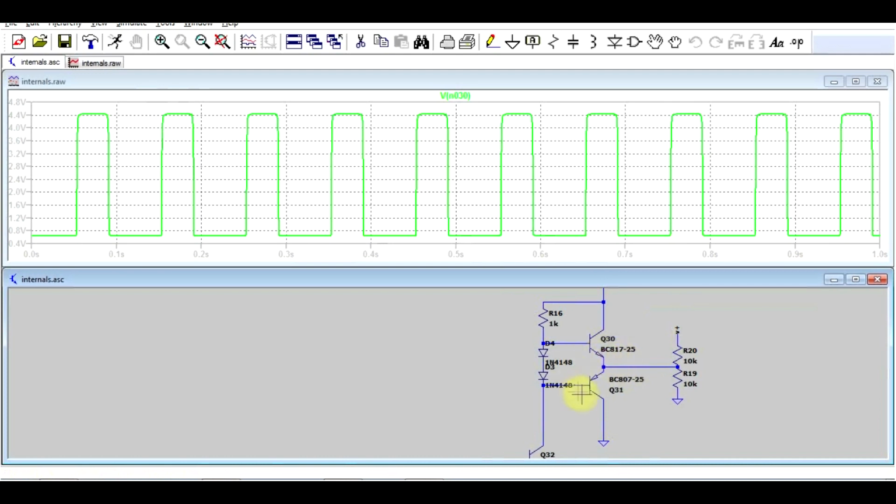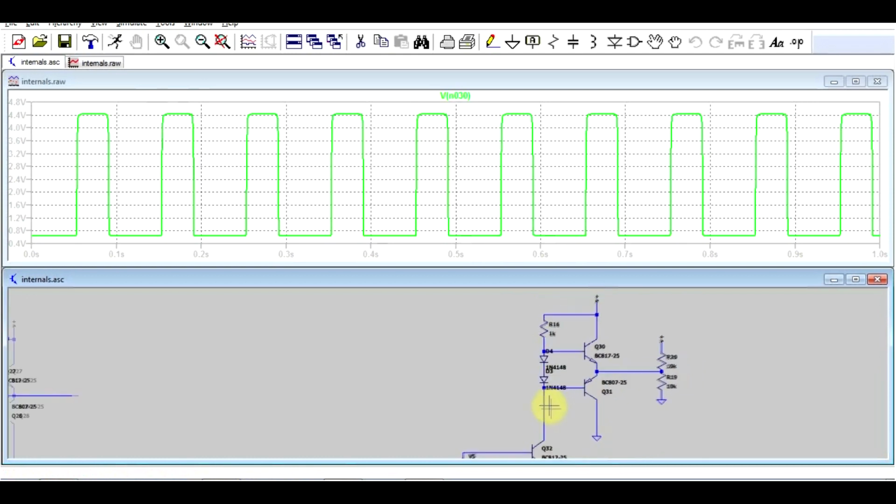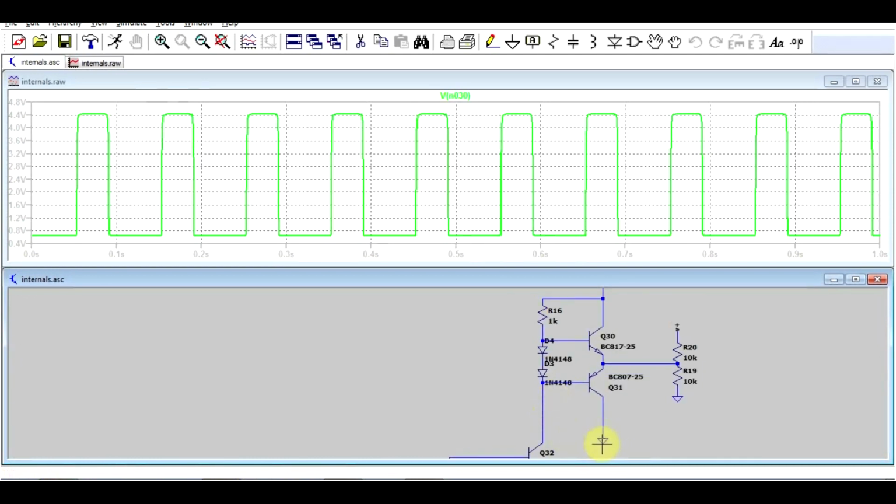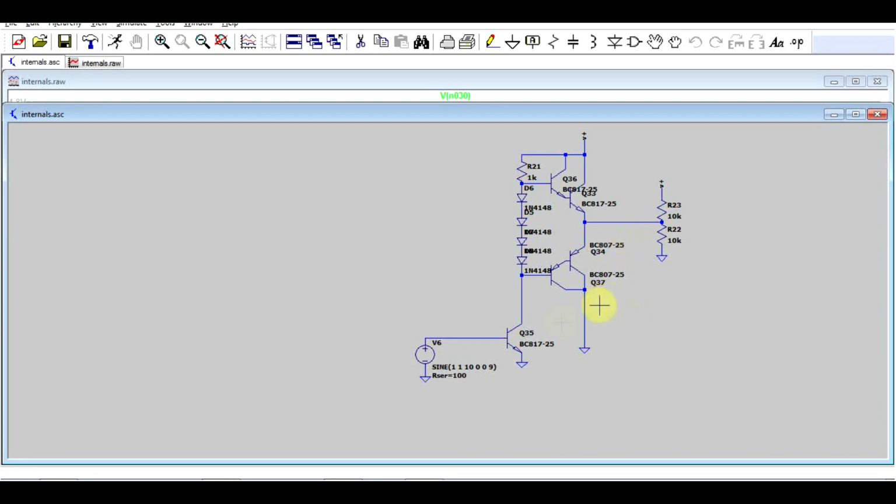The exact same thing is happening on the low side transistor. So if we drive the base of this PNP transistor to ground, so the minimum voltage at which the stage is supplied, then the emitter will always be 0.6 volts higher than the base, giving rise to this low voltage limitation. Now in more complicated output stages, which have been designed to handle much higher currents, for example this thing,